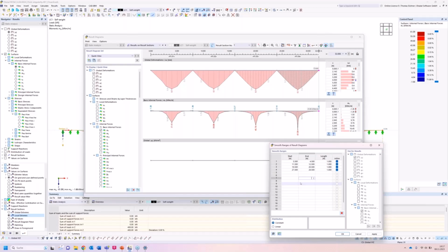So when you have a column on a slab, you firstly model it just with a point load, just because it's simple. But in reality, it stands on a square meter or 0.5 square meters, and this point load is distributed on this column section surface. So that would be a thing.